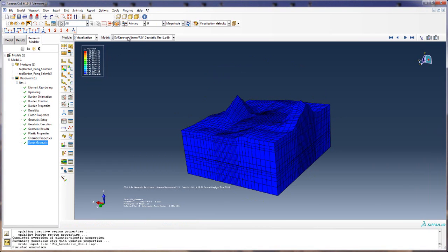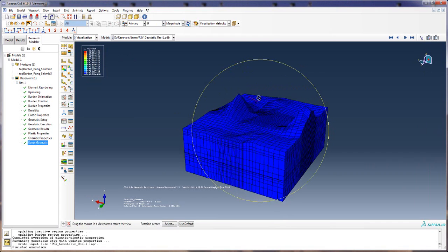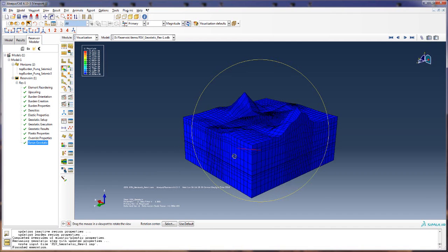And we see a very small set of displacements, 1e to the negative 6. So when you're talking meters, you're talking about 1/10 of a millimeter, something like that, or 1/100th of a millimeter. So that's what we want. We wanted to see that this thing is in equilibrium. We don't see a lot of deformation because presumably this data is exactly in equilibrium.